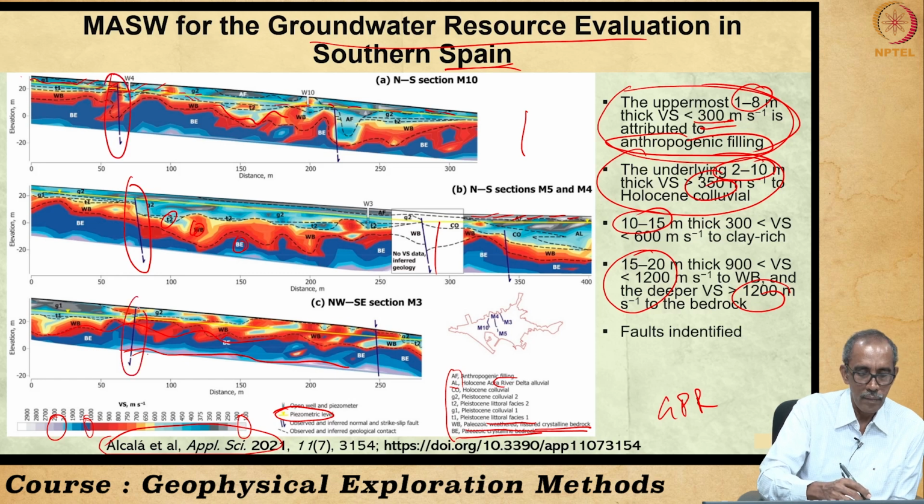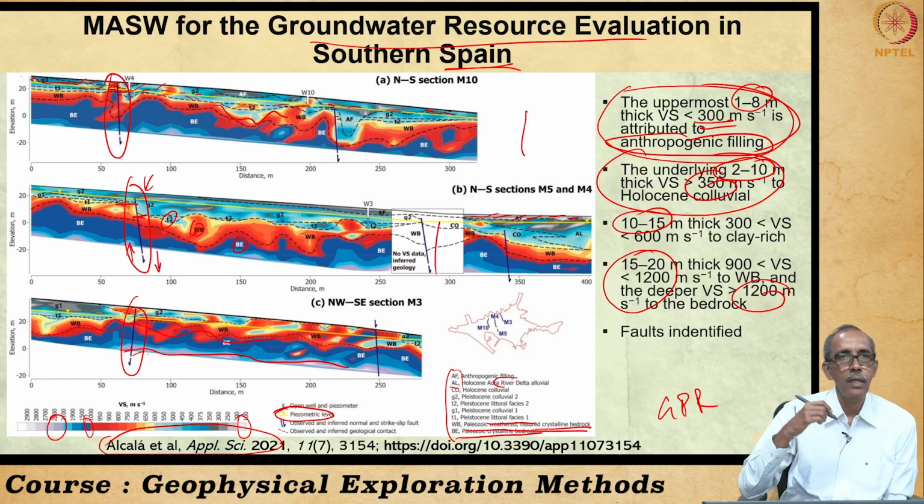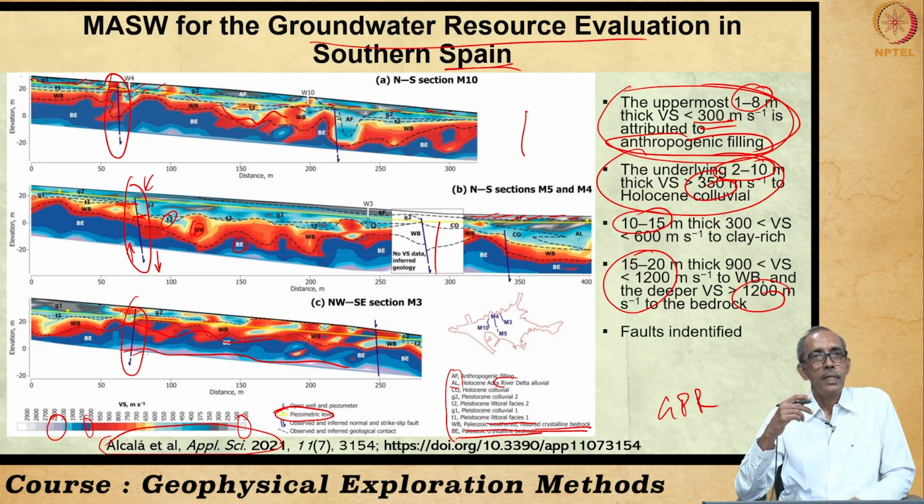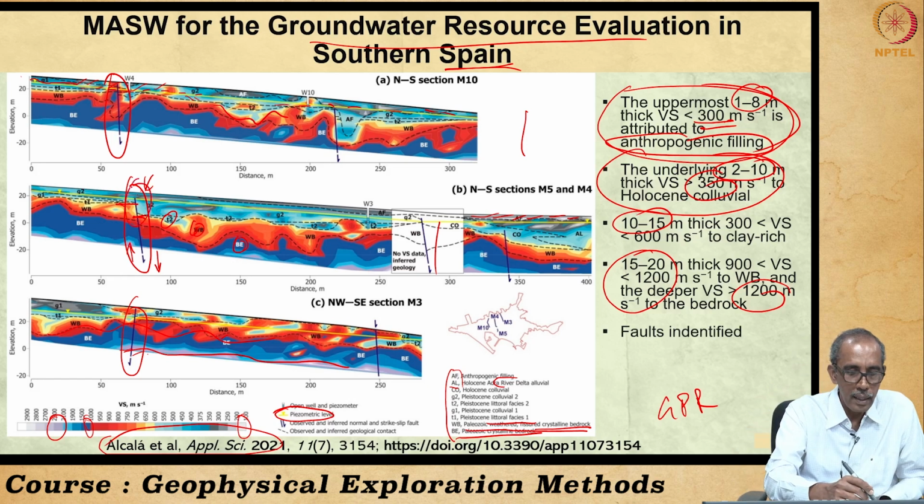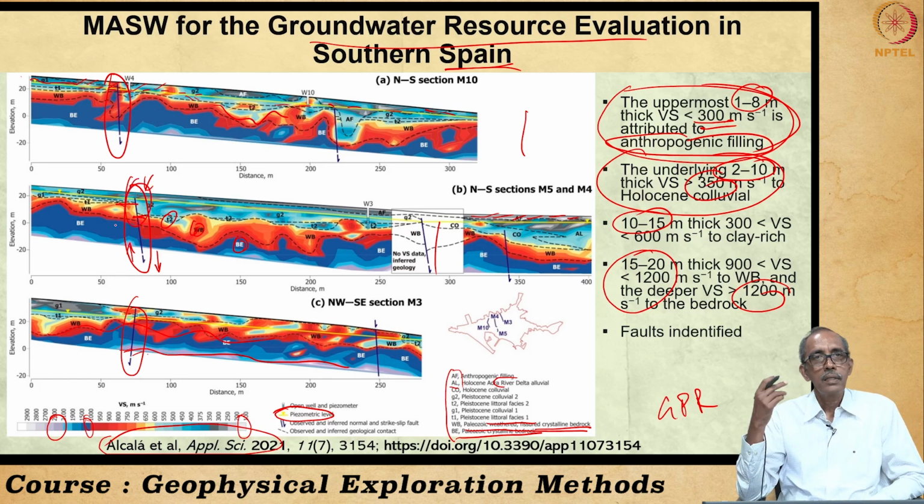You can see, right, especially this one is very interesting, right? Here you can see there is a marked change in the level, indicating this part of the earth has moved downwards with respect to the rock on the left hand side. You can literally see something like a staircase here. The velocity distribution is able to show us a major structure, which is a fault.